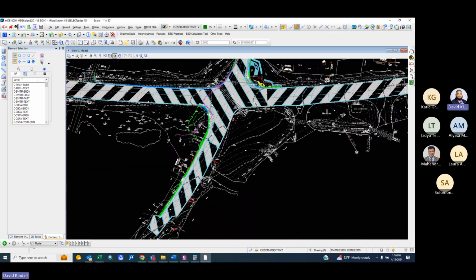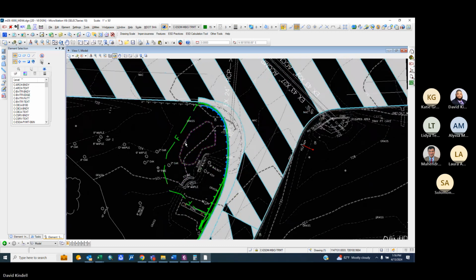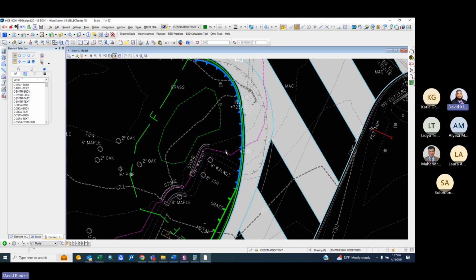So when highway puts curb and gutter, and we start one facility here, what do we do? How do we fix that to make sure I'm having impervious area drained to here? So what you do is tell highway, okay, we want to put maybe a curb cut here in order for water to get here.